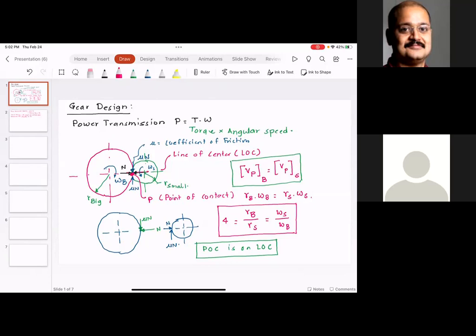Have you seen that happening? The chain just flies off. So belt drives are more forgiving because basically they can deform. And there are design philosophies. For example, people started saying, yeah, belt drives are forgiving. Chain drives, basically, they are positive power transmission. So how do we combine the best of both worlds? And they came up with a timing belt.